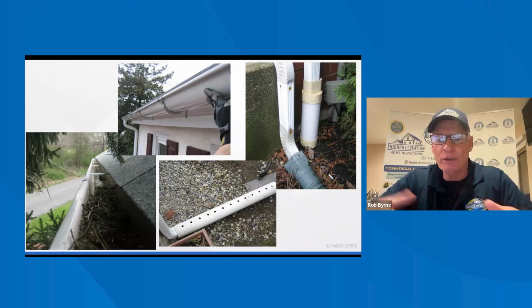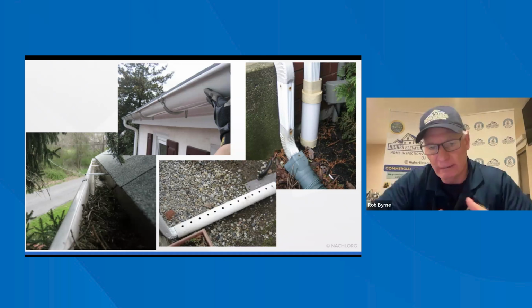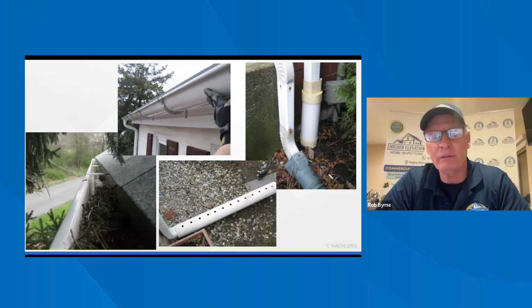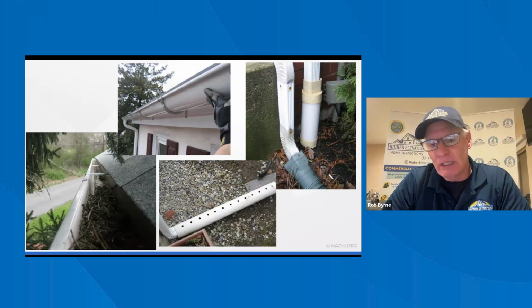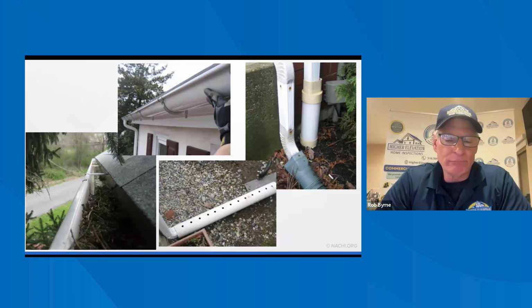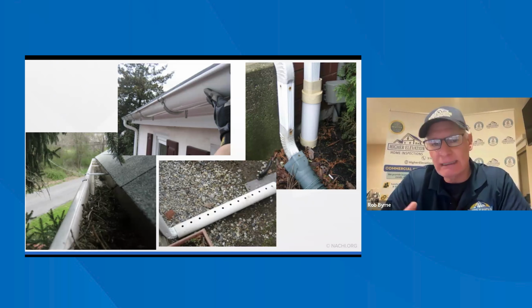You'll see it's all eroded from that water just running off the roof and hitting the ground. And then, of course, it builds up water against the foundation. It gets wet. That soil becomes heavy, moisture laden, and then you just get that hydrostatic pressure that pushes in.